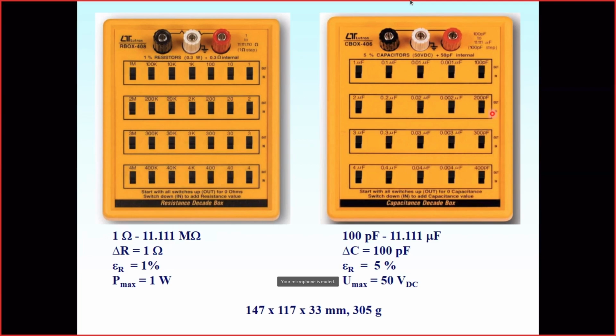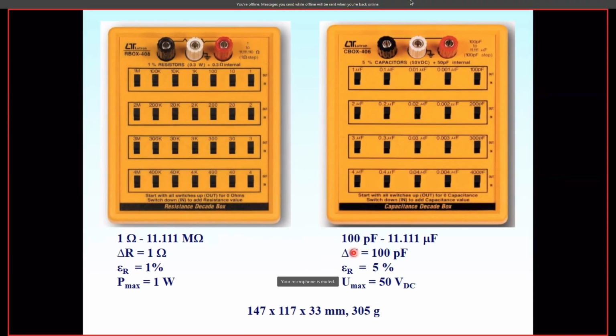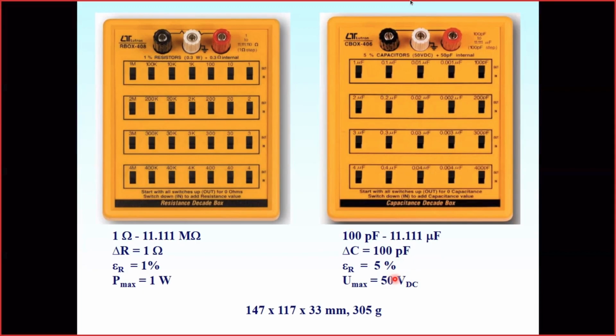Here is a similar box, but for capacitance. It provides capacitances in the range from 10 picofarads up to 11.111 microfarads in steps of 10 picofarads, with an accuracy of approximately 5%.